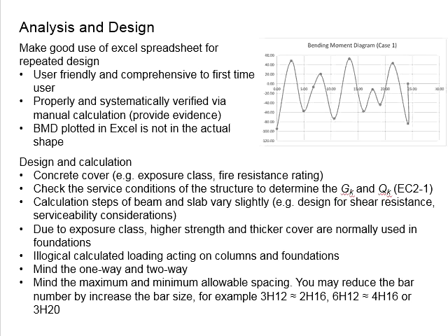What kind of materials are being used, through some basic calculations in terms of the amount, and you can refer to Eurocode 2 Part 1. In the list of the appendix there are densities of the materials. From there, with some basic calculations, you are able to estimate the Gk. Through those estimations, you can choose to slightly round up the number for yourself to have some margin of safety in terms of the loads acting onto the structures, and justify the value that you use.